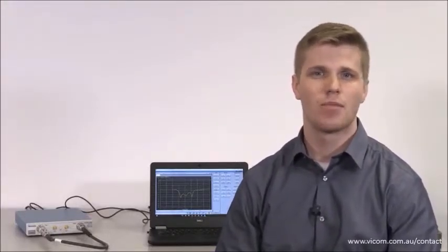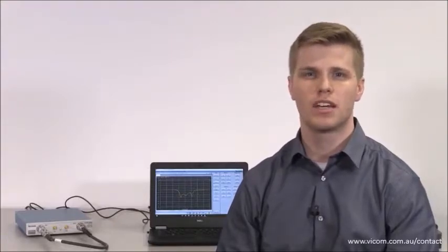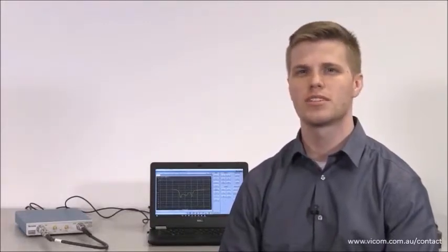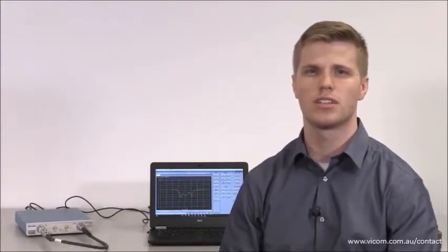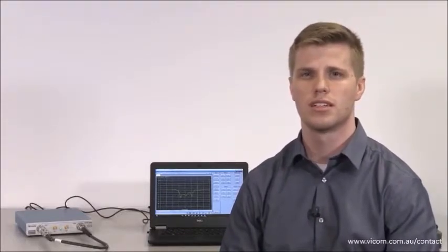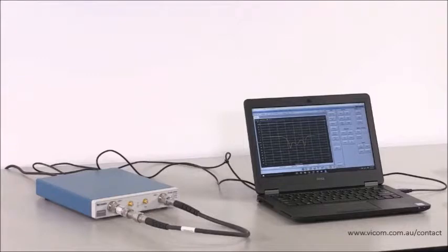In this video, I'm going to demonstrate how to make a phase and group delay measurement using the TTR500 VNA. Phase and group delay are two measurements that can be used for determining if there's distortion in your device or network of devices. In this setup, I'm measuring a bandpass filter using a two-port measurement.